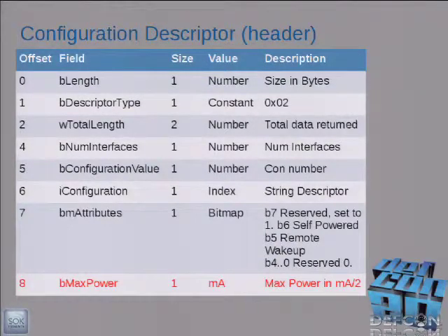Now, if you're going to make a little device, something kind of like this little preview, that is going to fake another device, obviously I have some electronics that are going to require a little bit of power of their own, in addition to whatever my thumb drive takes. Some people might be tempted to just crank up that power. Don't do that. The problem with that is if you crank up the power and your port cannot provide that much power, it won't enumerate your device. So usually 100 milliamps is pretty safe, and it's probably enough anyway.